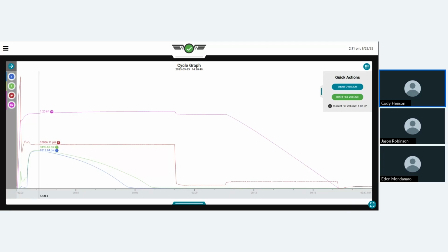So if you're running a D2 process and you have a machine triggering, this isn't as critical. But if you are running a D3 process, this is what tells the CoPilot that fill has stopped and that the pressure stage has begun. Because without a trigger from the machine, the CoPilot doesn't have a sense of when that happens unless we tell it when it happens.